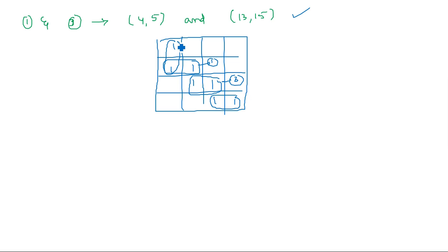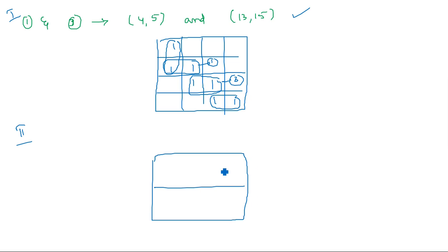Okay, this will be the first essential prime implicant, and this is the last essential prime implicant. These two are common. Along with these two, we can take these two. This is a selective prime implicant. We can select these two. Or another combination is first set, and second set. What do you mean by second set from this?